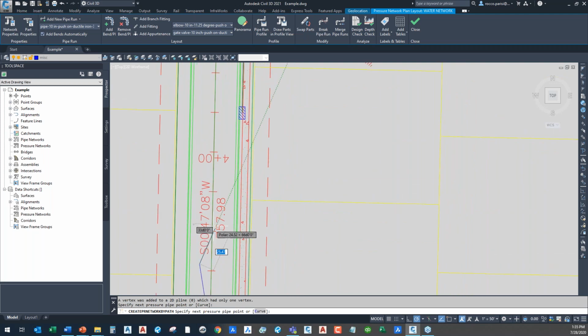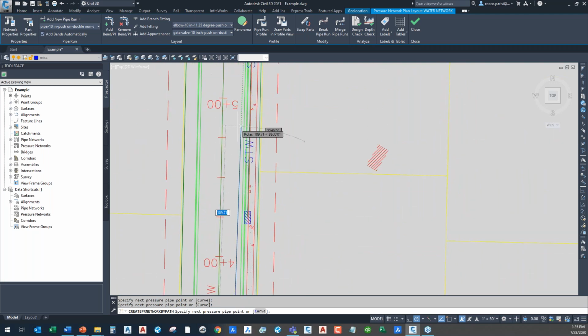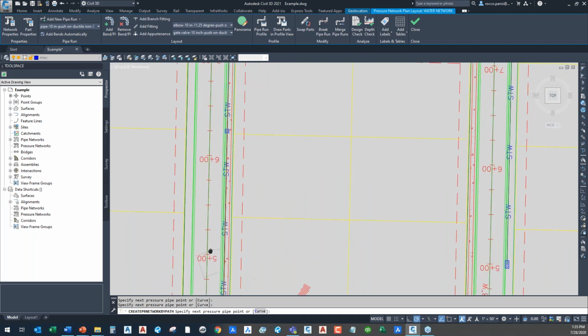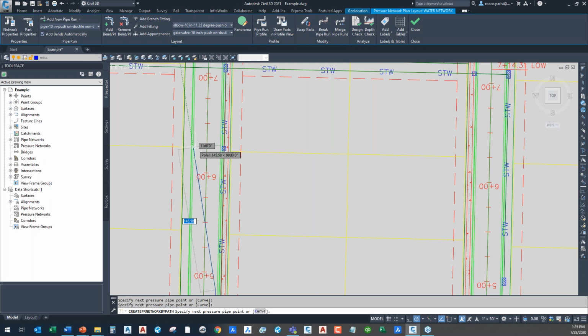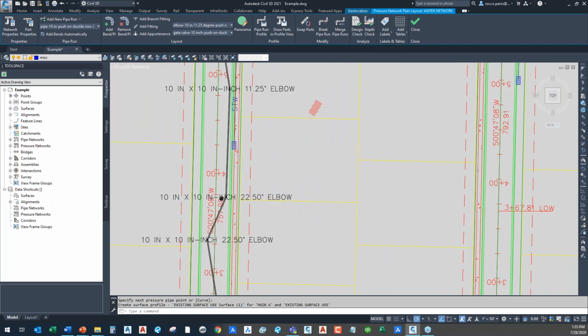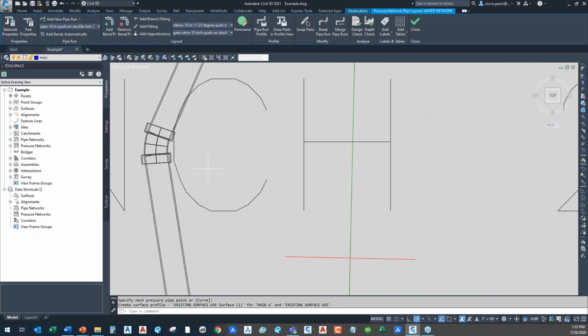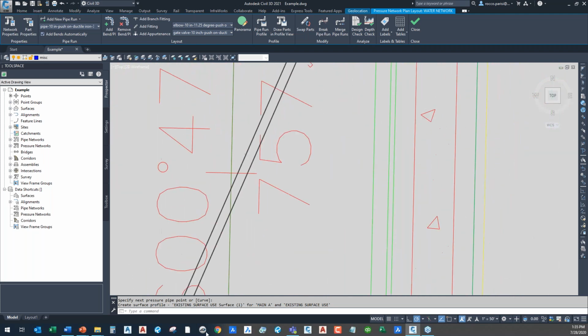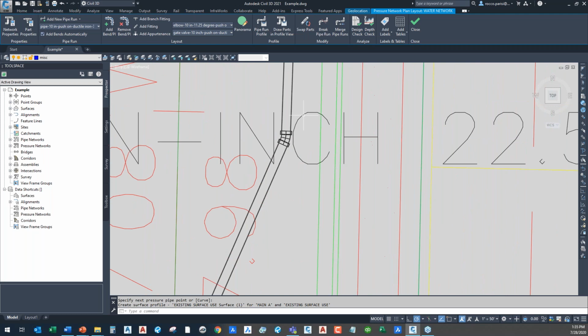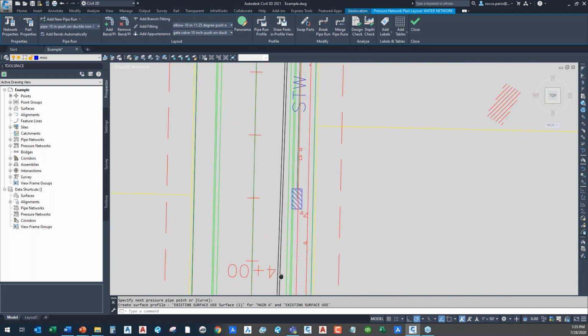But you notice that as I start changing and modifying designs, I'm just working my way up here to set angles, and then I'm turning to wherever I need to be for different set angles wherever I want them to be here, and I'll just throw one up here at the end and go good enough and end that run. And you see that in the new version here, it's automatically putting in the correct size elbows for me based on my drafting settings. So it's shifting me between them.